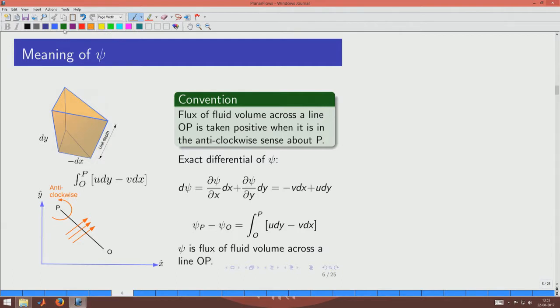Okay. So, I take a line element like this. This small line element between O and P will then be given in terms of its components dx and dy, in two perpendicular directions. Now, in the vertical direction, if you have unit depth, which means that we are talking about flow through this plane. You could see that the flow through that plane can be thought of as flow through the two planes that we are indicating here. One is through this and another is through this.